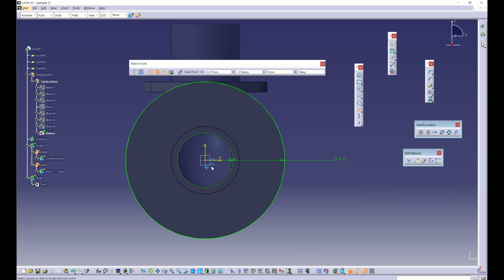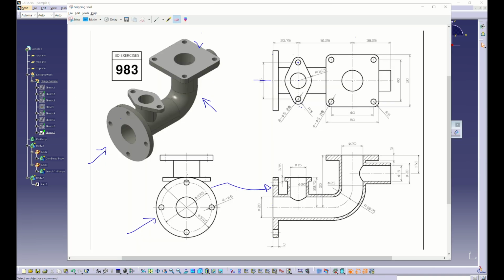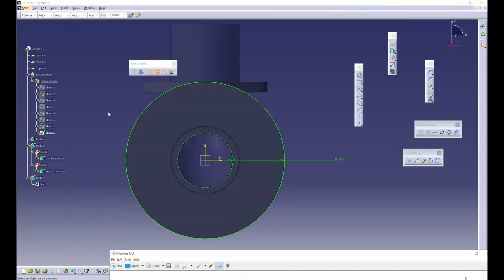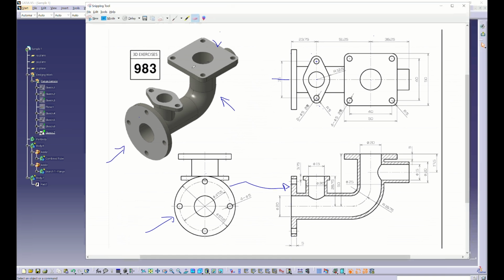since I wanted to show you how to use another function, circular pattern, instead of integrating it into one or doing it inside the same sketch, what I'll do now is to segregate it. So we have four patterns here, and the diameter used for its center is 47.5.